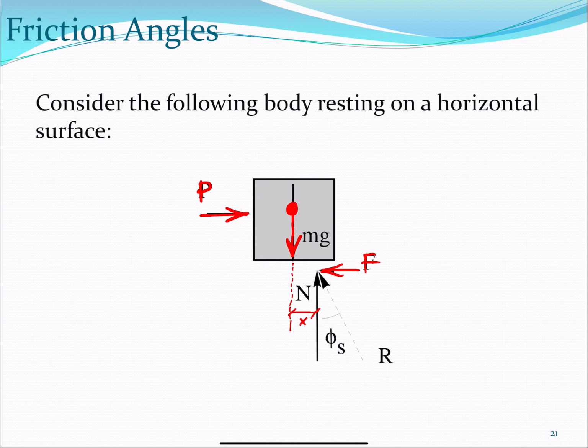But just to show you that indeed that normal force has to move, I want you first to imagine the case in which there is no load acting on your body. So the weight acts here at the center, and the normal force is aligned with the center of mass. Right? So imagine rocking is going to happen. This box is actually lifting a bit, or about to lift, but you get the idea, right? So it's about to lift.